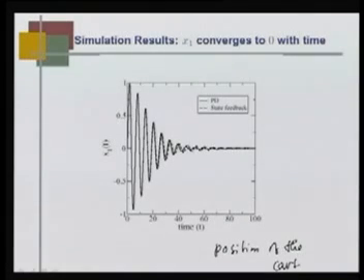Okay. You give some little disturbance to the cart, finally, it should come to the rest position. So, what is the meaning of PD? This is the FLC controller where we have used the PD type of rule base, that is if x1 is ... x3 is positive and x4 is positive, then u is negative in that kind of rule base.